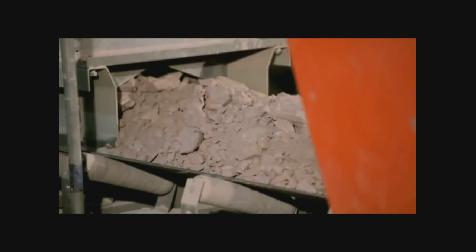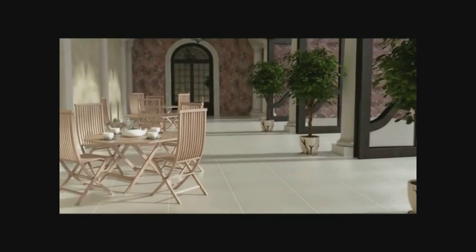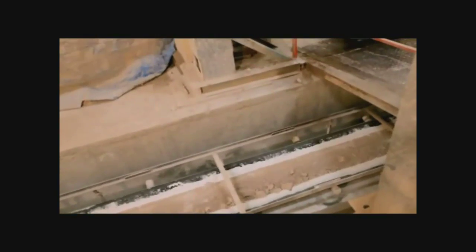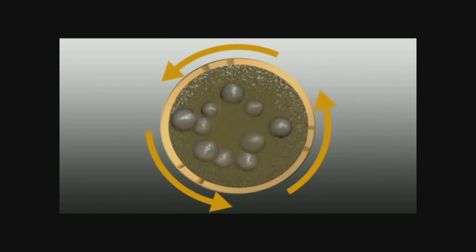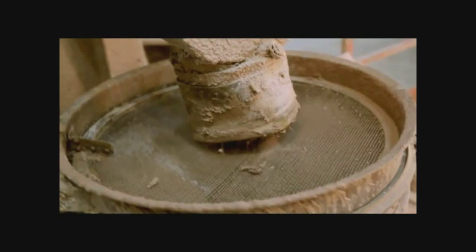The plant uses some of the finest imported clay sourced from Ukraine, the most expensive clay in the world, prized for its strength and plasticity, ensuring that you get tiles that deliver long-lasting strength and beauty. Raw clay powder and other minerals are combined in a batch mixer for complete blending. The mixed clay and mineral chunks are then further crushed and mixed with 33% water in specialized ball mills. Inside these cylindrical drums, giant alumina balls crush the powder to create a homogeneous paste-like mixture.